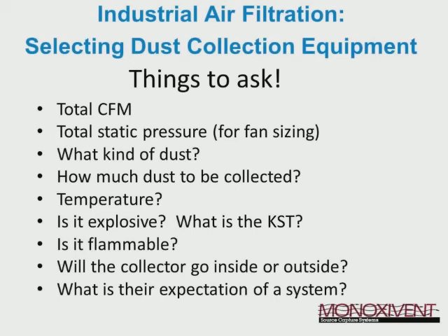All right, so things to ask when you're designing a dust collection system. Total CFM. What do we need for total CFM? What is the static pressure? Because that's what we're going to use for designing our fan. What is the dust? What is the volume of dust? Is there temperature concerns? What is the temperature of the dust? Is it explosive? Is it flammable?